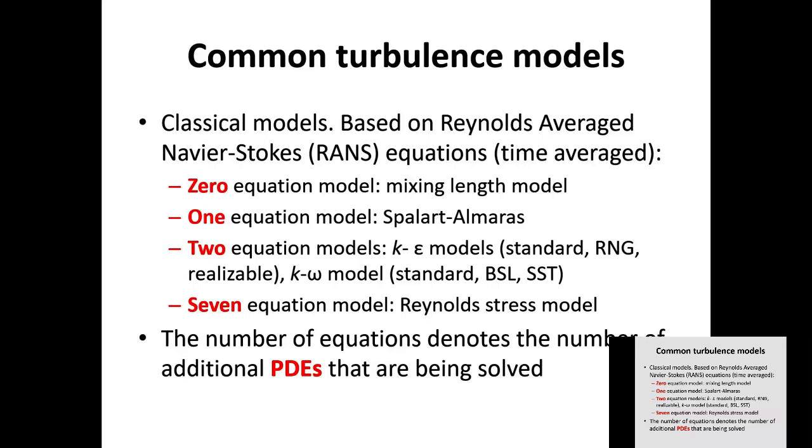And then you can have a seven equation model where you resolve the Reynolds stress completely. That is a Reynolds stress model. When the number of equations increases, the number of partial differential equations that you need to resolve increases as well. That means this model here is more time consuming than these models.